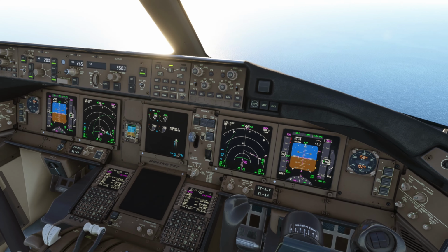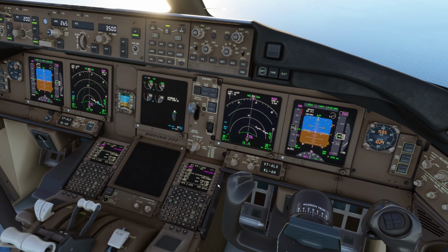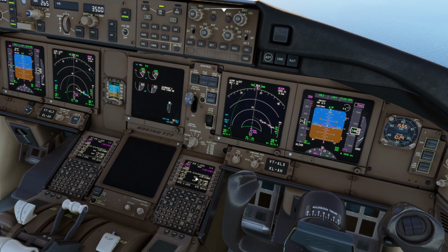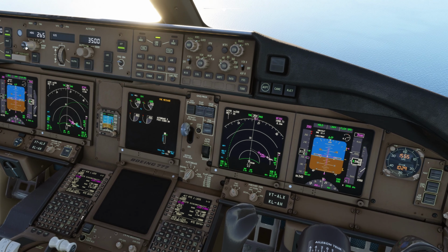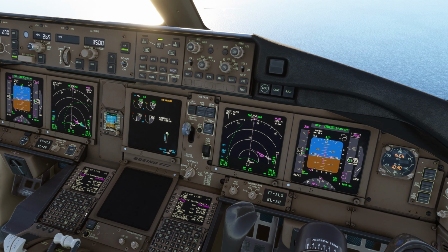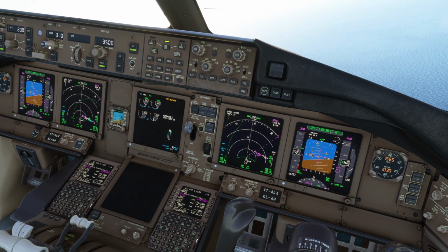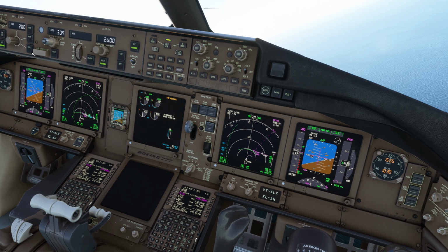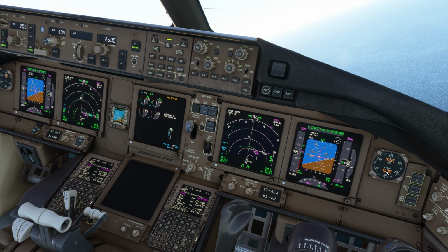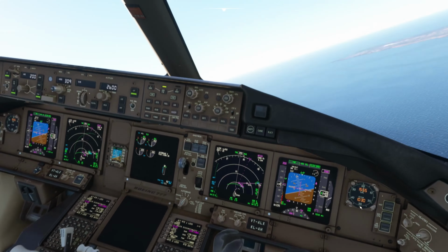So the ATC has said 3500 or above at Dixon, then we are cleared for the ILS approach. So it says at Kilo Foxtrot 101, it says 2500 above. Discontinuity, heading select, and I'll proceed direct towards Kilo Foxtrot 101, and it says 2500 above, so I'm going to set 2500. Flight level change. Discontinuity checked. Thrust, heading select, flight level change speed.